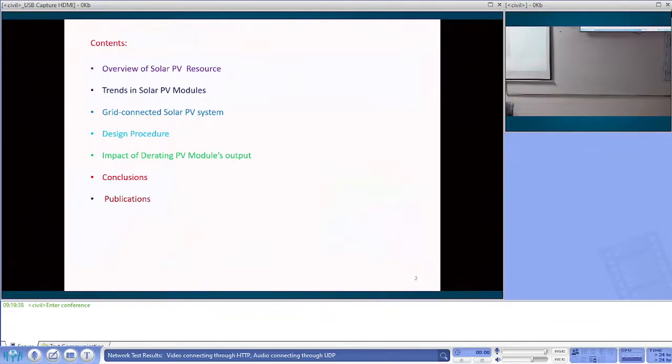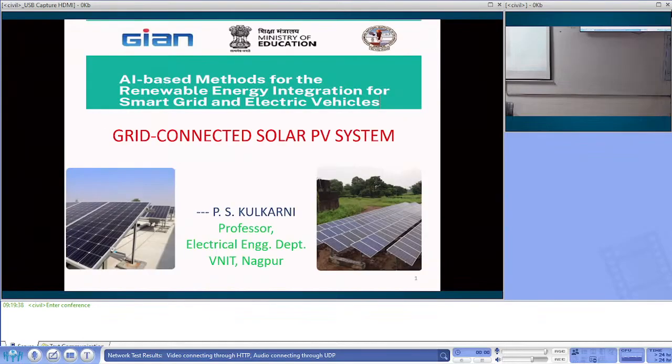First, the first part in the plant is the solar panels, and what are the advances in solar PV technology? Earlier we had monocrystalline and polycrystalline. Polycrystalline modules you will find in a number of installations, whether it is a standalone PV street lighting system or a grid-connected system. Monocrystalline you will not find to that extent. It has slightly higher efficiency.